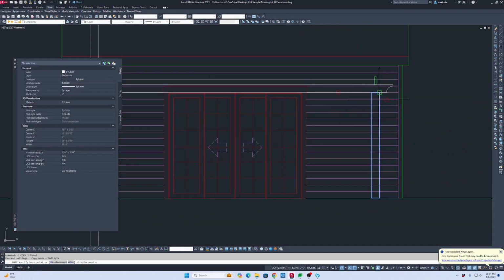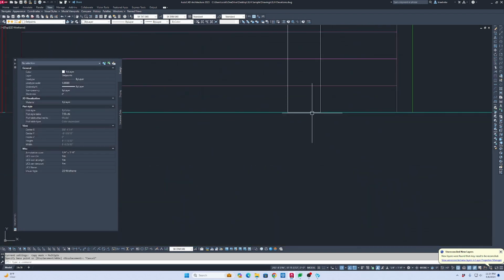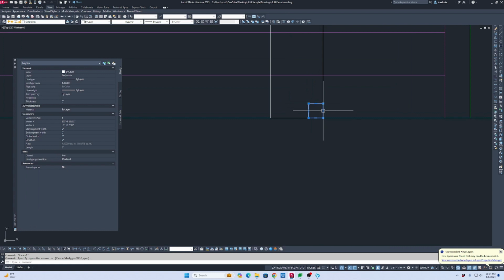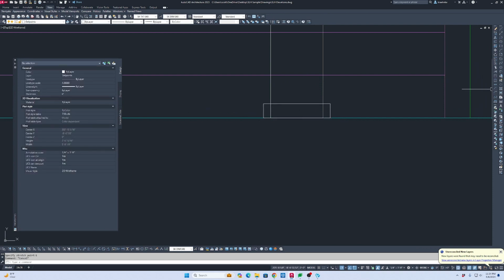Copy this rectangle. Oh, let's do the foot first. How big is this? 2 by 2 maybe? Yeah, that looks plenty big. Have this come out, what, 1 inch? And then let's do the chamfer command.